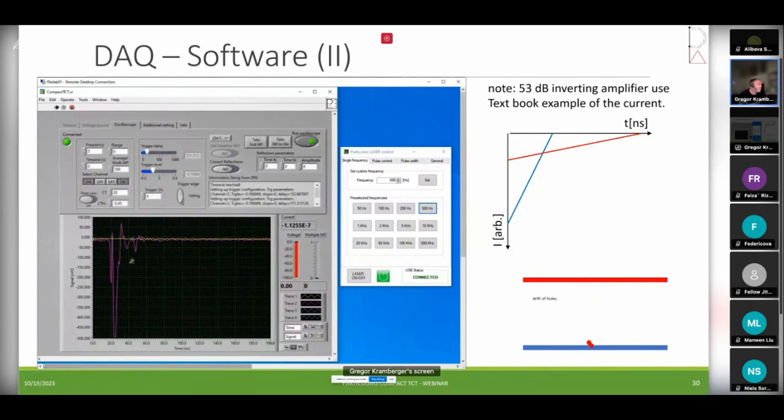See again, no signal at zero bias. You can shift the trigger in and out, so where you want to have it. You can also, if your trigger has a jitter, which some digitizers or oscilloscopes have, correct it in the software also, so that you get a very, very fast rise time, with no jitter or minimum jitter here.